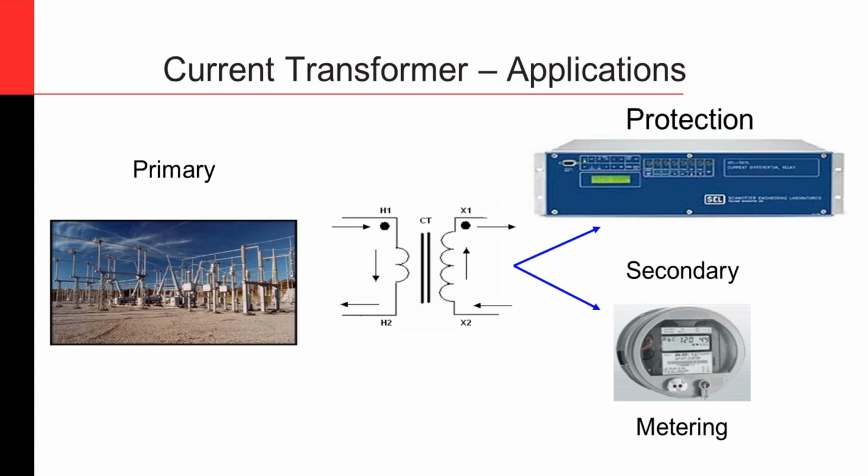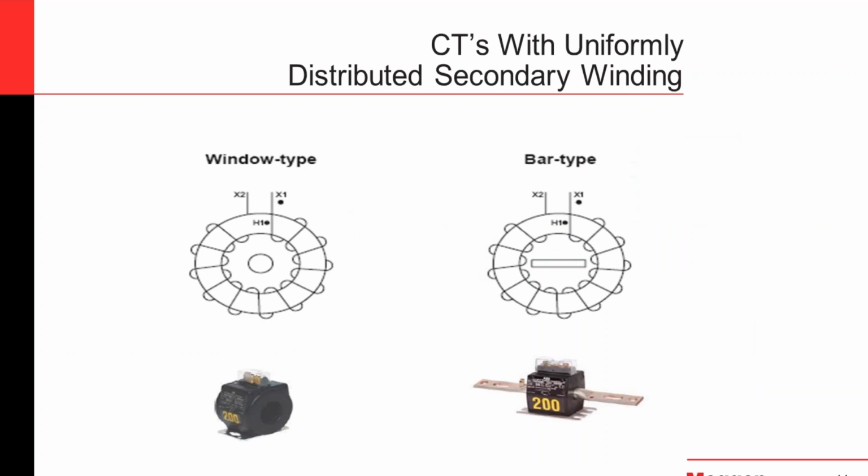I would also assume that CTs and PTs are kind of like the sensors of the system, which constantly monitor your primary values and tell you the corresponding secondary values on your system. So you can use it in your SCADA system from the relays, and you can also use it for any other control functions that you want to do based on the readings from the CT.